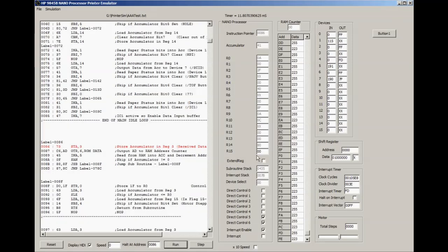If we now run this through, we'll stop as soon as we hit this address. Okay, I'll do this a few times, and each time around this loop it will input this data through the input buffer and latches, and it will write it into the RAM. So we'll see the data is now appearing in the RAM, and each time we go through the loop we'll see the data appear. Again, this is decimal, and this time it's not inverted, so this is now a value of 65, which is 41 hex, which is the value for an uppercase A.